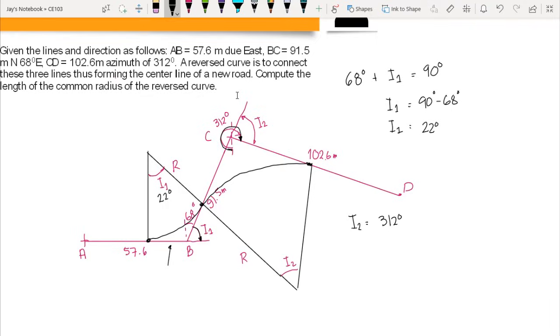Minus 180 degrees. So from the south to this point, that is 180 degrees, correct? So minus 180 degrees, then minus this angle here, and we know that this angle is equal to the angle at this point, since they have the same reference line, and these two angles refer from the north.